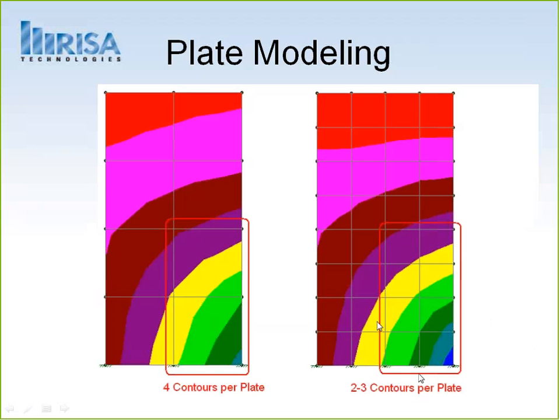And then when we start to submesh, we see that we are getting even more fine-tuned. This is the exact same model between the two, the exact same situation. But as you submesh it, you get a more fine-tuned answer inside of that plate, and you can actually see that there were higher numbers. We just weren't detecting them inside of that very large plate. So when you're looking at stress risers or things that are really tight in the area you're working with, you will want to submesh even tighter just to identify this issue.